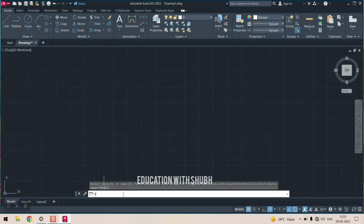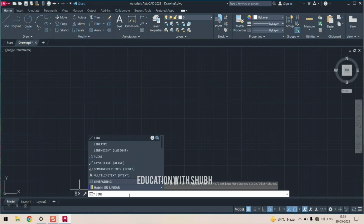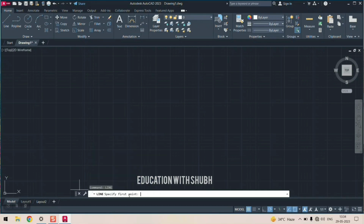So in AutoCAD there are 3 ways to give a command directly to the AutoCAD. First one is go directly to the ribbon and select a particular command. Second one is with the help of the command line. If you want to give a line command, you can just type line. It will create a line.